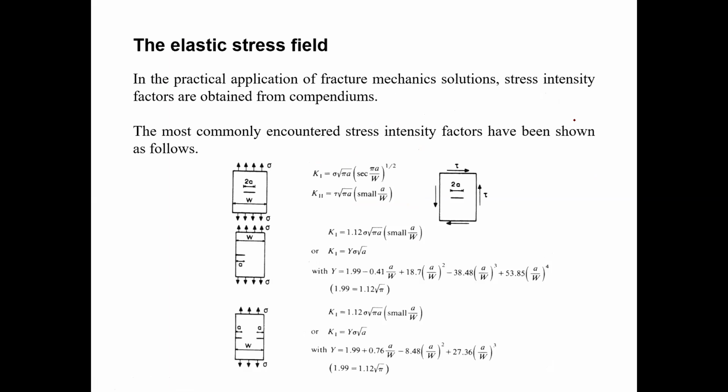And you can see here, if you have different kinds of loading conditions, here is the tensile load, and this is a center crack. So the location of the crack is also very important. You can see this center crack, and this is the width. In the question you need to be very careful to identify the location of the crack. So this is a center crack. Then you need to use this equation or this equation.